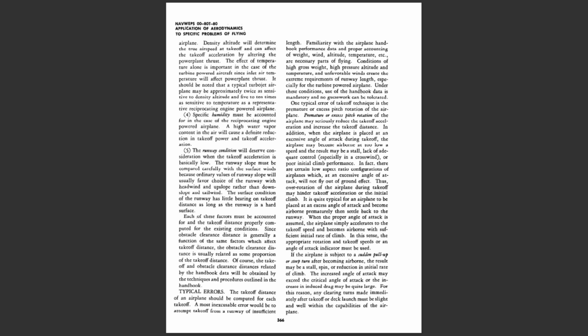5. The runway condition will deserve consideration when the takeoff acceleration is basically low. The runway slope must be compared carefully with the surface winds because ordinary values of runway slope will usually favor choice of the runway with headwind and upslope, rather than downslope and tailwind. The surface condition of the runway has little bearing on takeoff distance as long as the runway is a hard surface. Each of these factors must be accounted for, and the takeoff distance properly computed for the existing conditions.